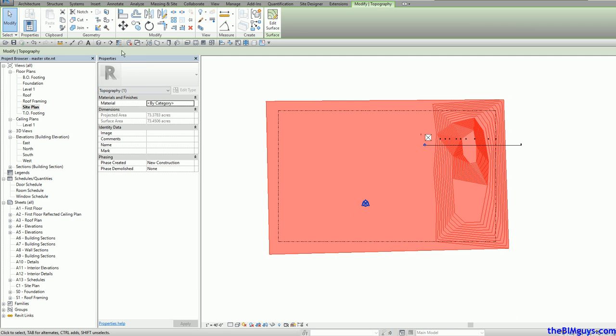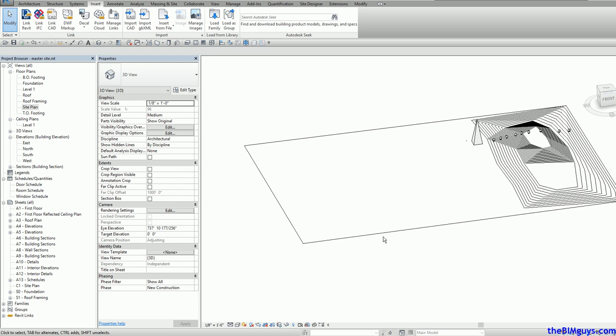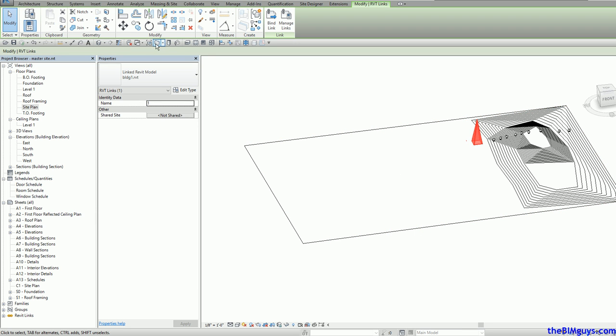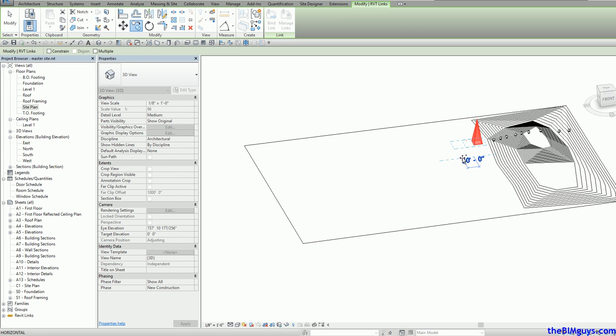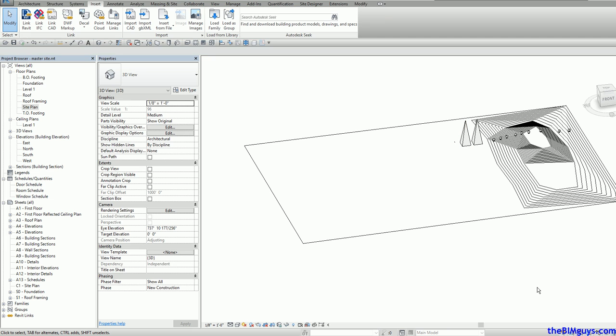So that is how we can get the site set up. And now here's the nice thing. If you have buildings that are similar, I could take this one and actually copy him. We didn't actually put a floor in him yet, right? No. That's just a matter of, like we did our walls. I guess you just add, there's a floor button too? Yeah, there's a floor button too. Okay. And I'll go back to that. We'll add the floor in.